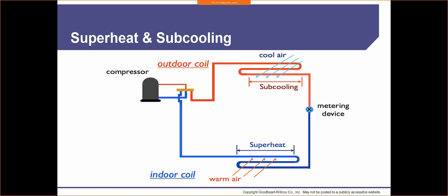The other thing too is when we are hooking up our systems, we're going to notice that there's a line. Our vapor line is going to be covered in insulation once it exits the evaporator, and it runs all the way on over to the condenser. And why is that important? All right, it's important because we have a really cold refrigerant that's traveling through there, and what's going to happen is that pipe, if it were exposed, it's actually going to start to condense.